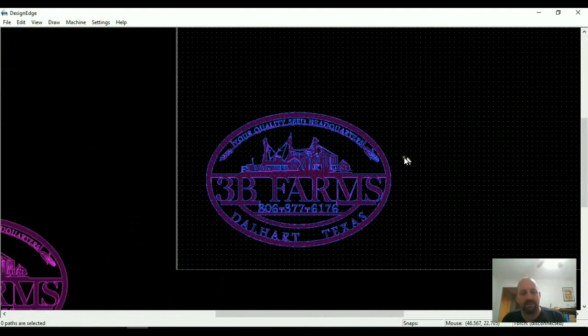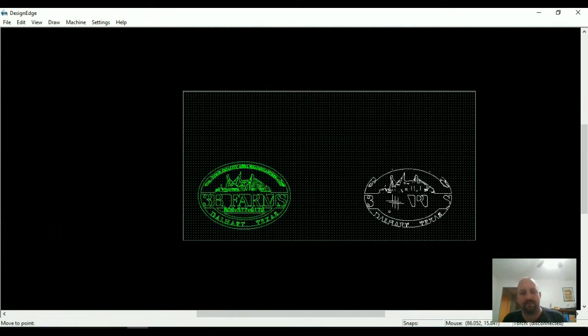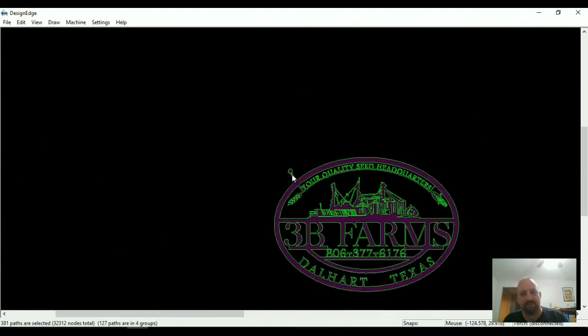So there you've got your complete cut path. I'm going to move that out of the way. F9 to turn those back on. Move those out here. I'm going to delete my little reference circles.